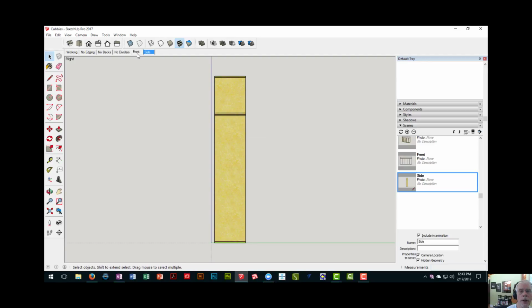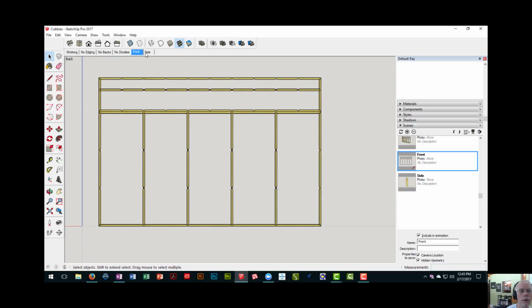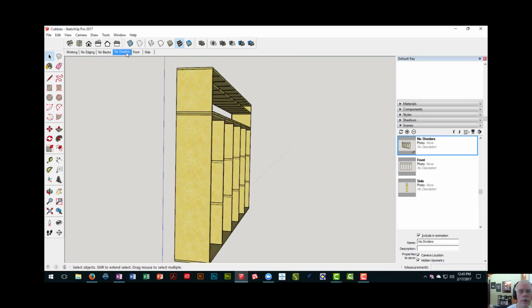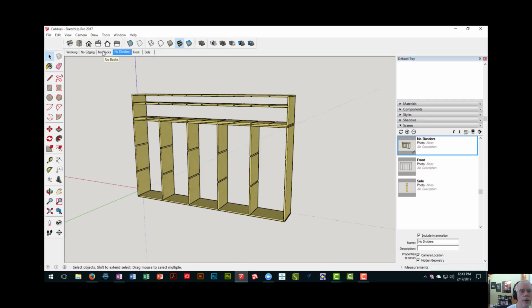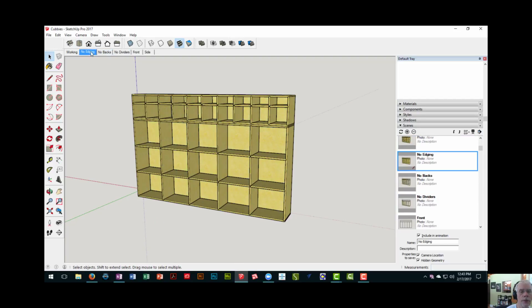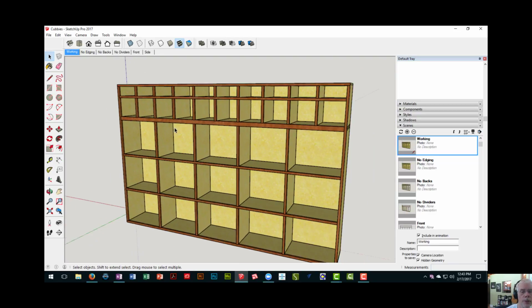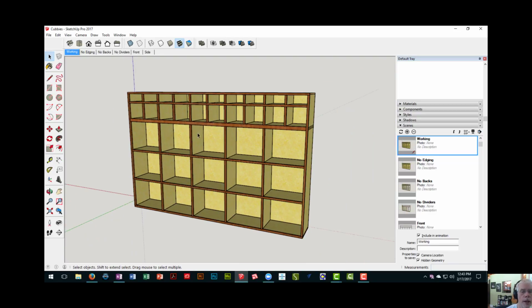Okay, so very quickly we can navigate this model going from the front to the side, or this perspective view that adds different components back into the model. So you can play around with that, group things and layers the way you want, make scenes the way you want, and most of the time it's advantageous to do this as you're making a model, because then you can control these layers and turn things on and off without having to individually hide them.